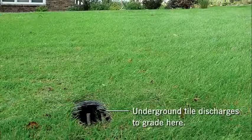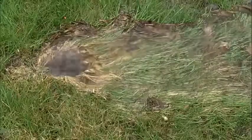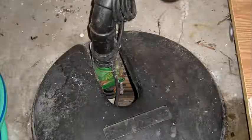In some cases, if the house is located on a hillside, these drain lines may be discharged at a daylighted outlet at a lower elevation, rather than to a sump pit inside the home. When homes with basements are equipped with sump pits for collection of the perimeter, below slab, or in-basement drainage, they require the use of a sump pump to lift the water from the sump pit to above grade level. Proper sizing, installation, and backup of the sump pump are important.